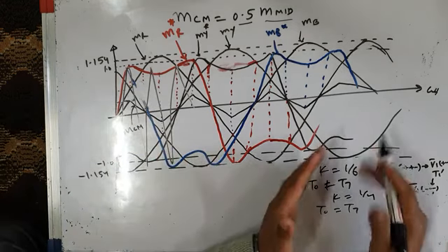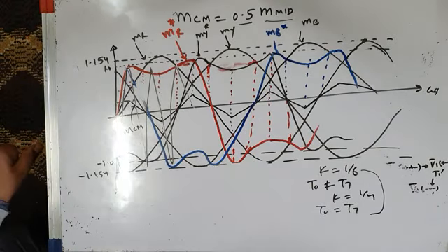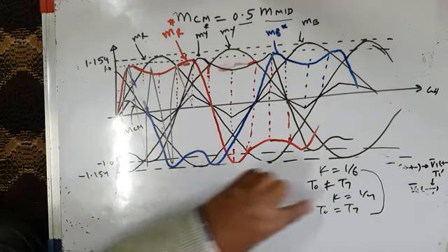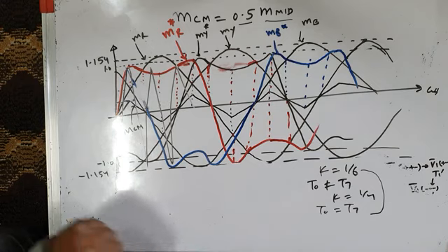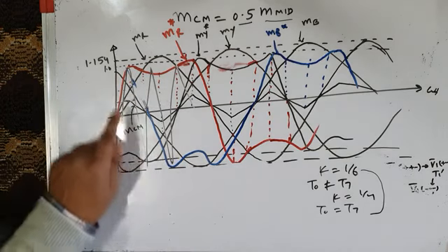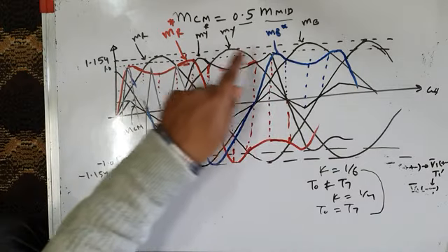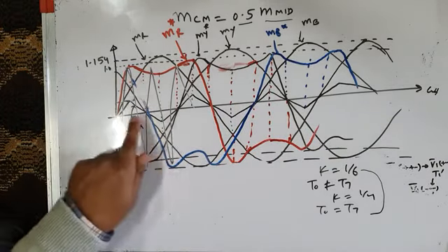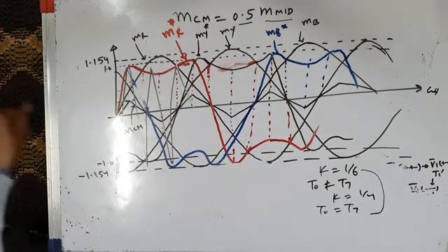So these two features were combined in space vector PWM, and we found that these two features can be combined in triangle comparison PWM also, if instead of having sinusoidal modulating waves, our modulating waves are modified modulating waves like this, MR star, MY star, MB star, which are obtained by adding to original modulating waves the common mode signal MCM, and the common mode signal is calculated like this.